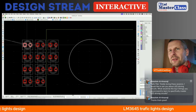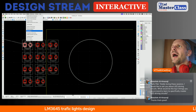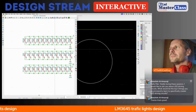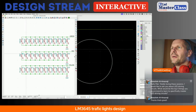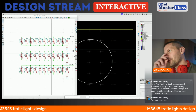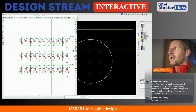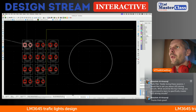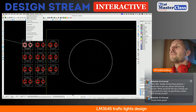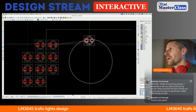I will start with the first LED. It doesn't matter, but I want to use the first one. And I don't like that we don't have a consecutive range of the designators. This will make some issues, but I will not spend much time here. Okay, so I will place this one. D2 is the first one, yes. And I will place it here,